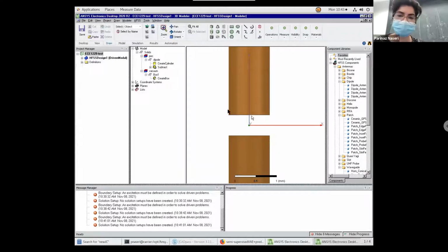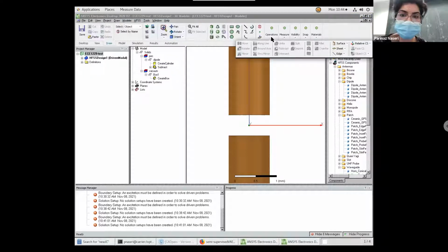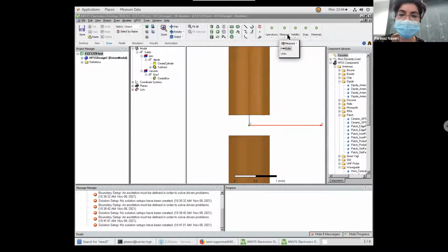So when you're trying to draw a surface here, it doesn't know where the surface is lying. Is it in XY plane? Is it in XZ plane? By default, it would go to XY plane here. But we want to draw the surface in ZX plane, right?